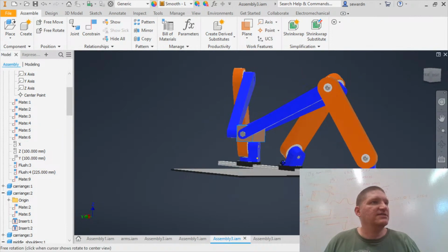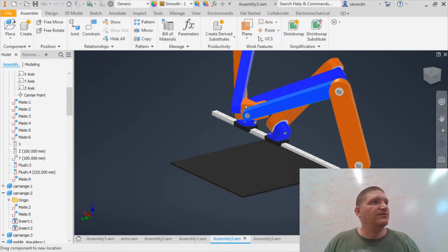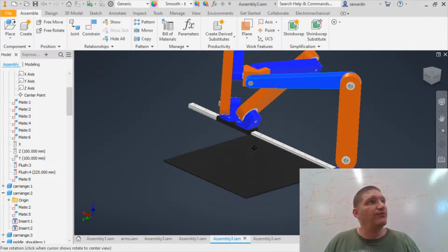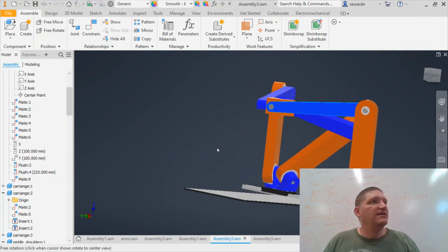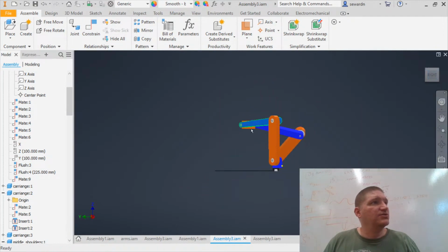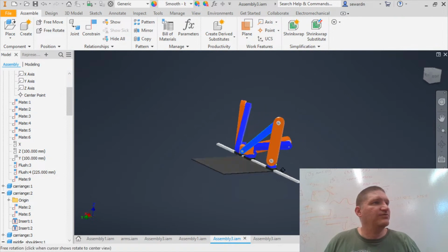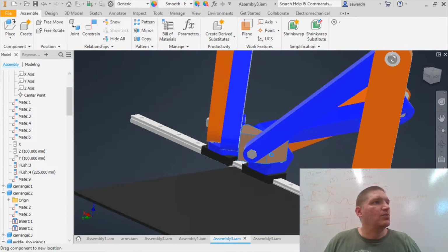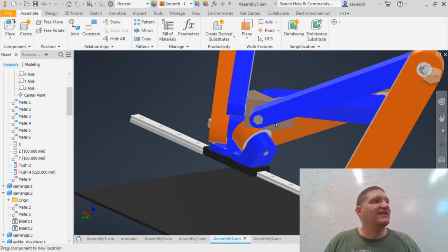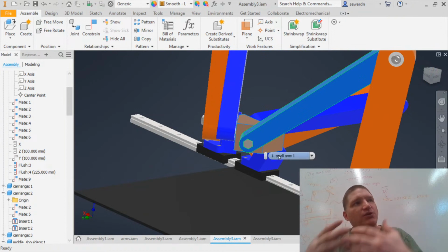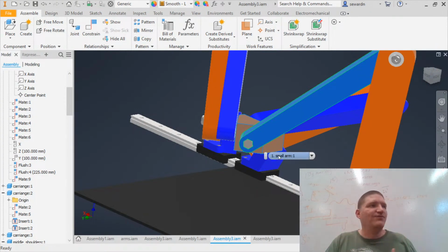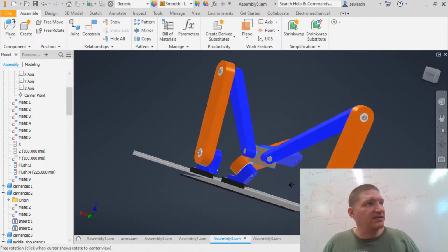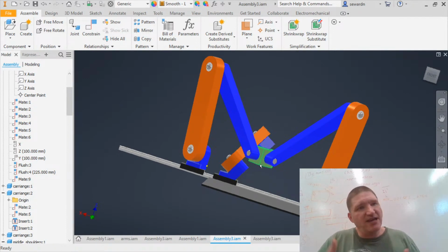Now I am constrained by the carriages. Once I go so high, I get a carriage collision right there, and I can't go any higher. As I come towards the Z, I have to go lower and lower to keep from getting the carriage collision. Let me see if I can get a good angle for this. Basically Z is 0 close to the rail, but you don't want to print close to the rail. As you move farther away from the rail, the Z increases quite fast because I picked a 30-degree angle. It's a pretty steep incline there.